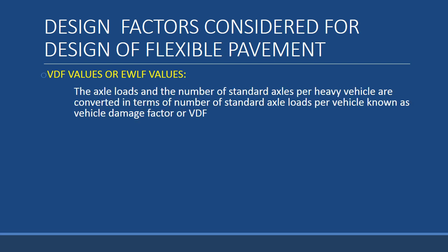The axle loads imparted by various vehicles have to be converted or represented in terms of the number of standard axle loads per vehicle, which is termed the vehicle damage factor, or VDF.